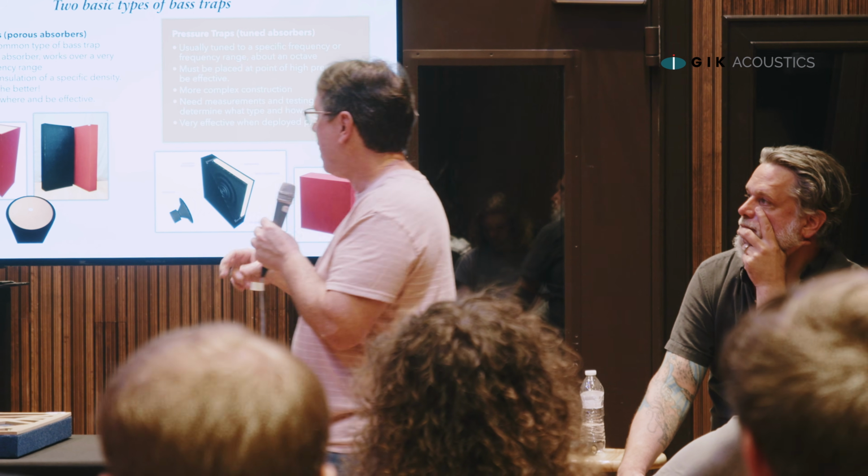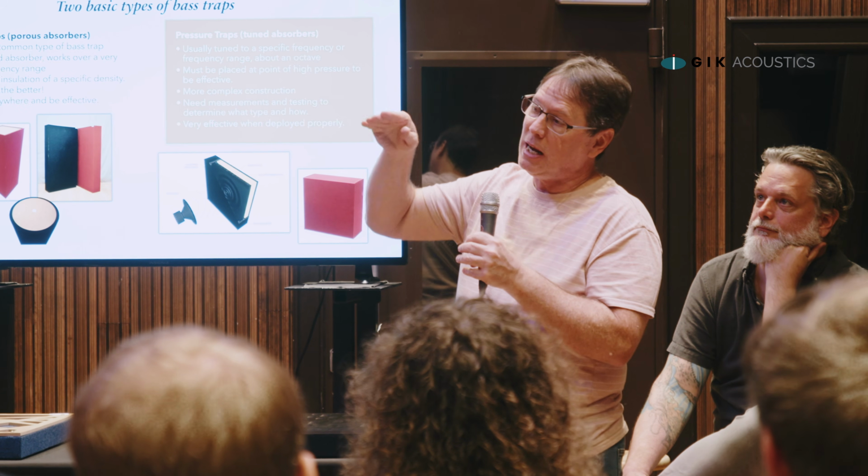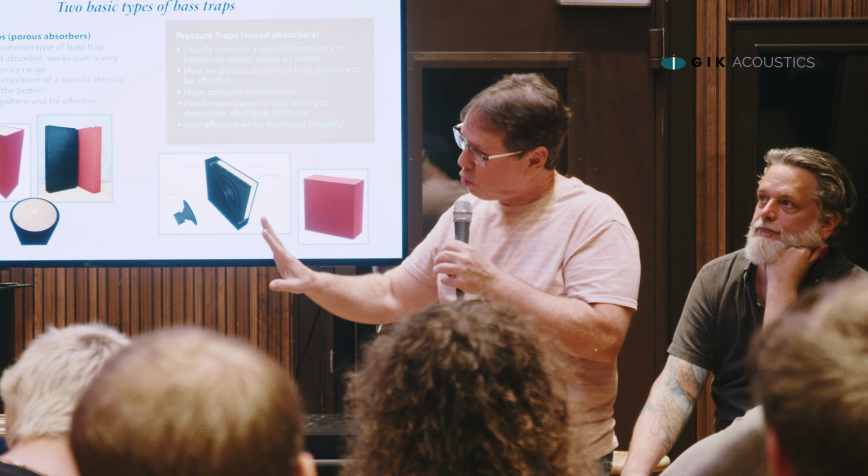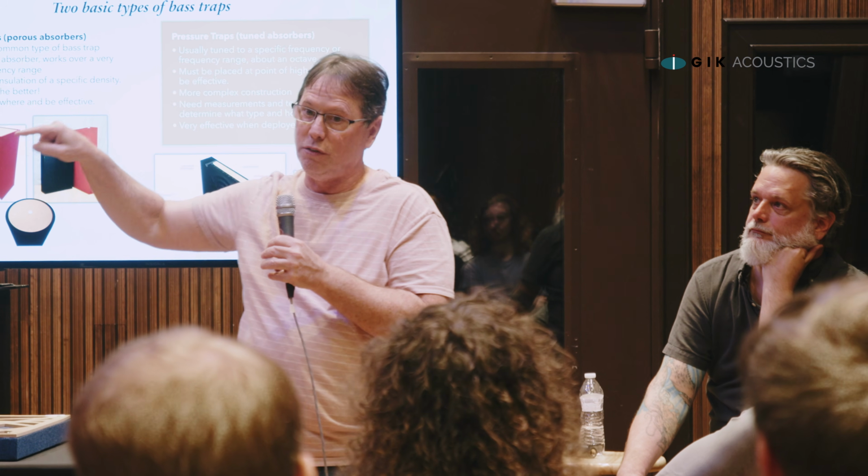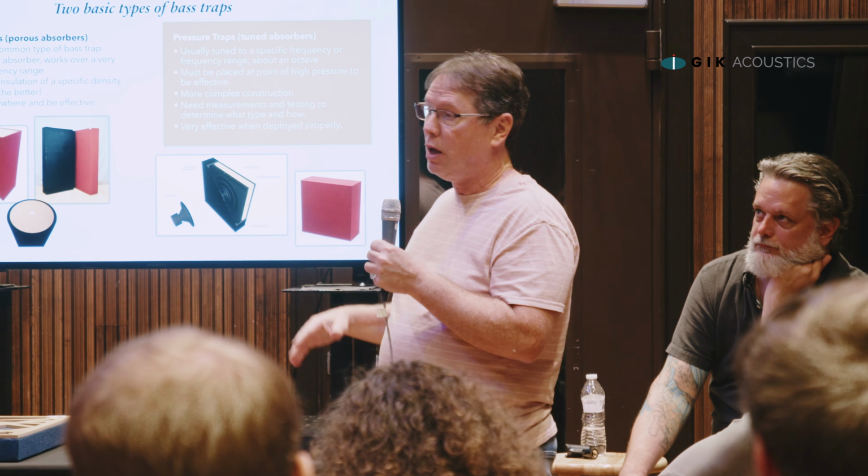You're leveraging a little bit of performance by the fact that there's an air gap behind the panel. An air gap can be kind of a multiplier of sorts. If you take an absorber and put it right on the wall, it's going to do one thing. You pull it a little bit away from the wall, it's going to work a little bit better, because that's a velocity trap, meaning it works better when that absorption goes to the point where there's movement in the wave. When it hits the wall, there's no more movement in the wave. Pressure goes all the way up. Velocity is at 0, and then it turns around and goes back in the other direction. So if you pull it away a little bit, we've just used distance to get better performance out of something, and it cost us nothing, aside from a little space in the room.